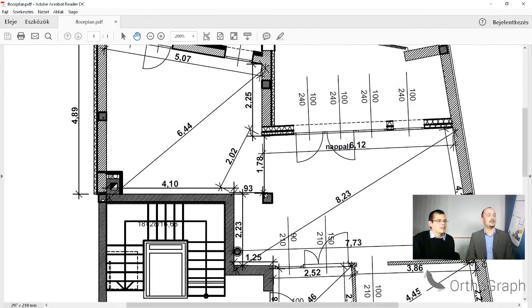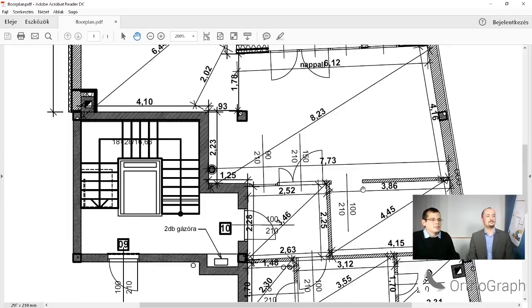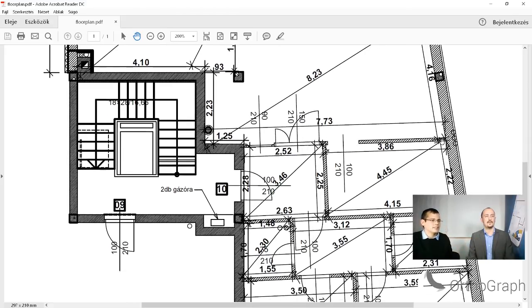That's right. So now here's where we are. Before we proceed, there's a very important thing we come across at this point. We see that there's going to be another room here, another room there. Now if you have a paper-based floor plan as I do right now, I know that this wall is one continuous wall, and I see how the rooms align. Now, if you are doing a site survey, especially in an older building, you might not know for sure if this wall is aligned, so you can't really sketch the next room closer to the first one the way I did in the beginning, because you can't know for sure if this is how it's going to align.